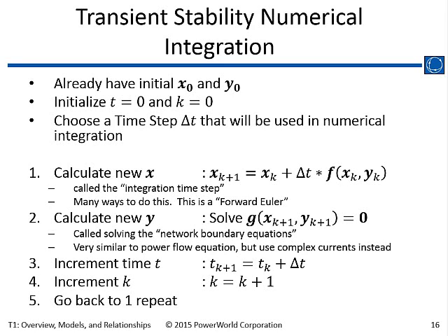The time step could be shorter than a quarter cycle. It could be longer than a quarter cycle. The problem is if you set it much longer than a quarter cycle, you can run into numerical instability issues where your system itself is stable, but it looks like it's unstable because the integration method is not numerically stable. You can run it shorter than a quarter cycle, but it just takes longer to solve. Usually the cases that you get have been tuned by somebody for a quarter cycle.